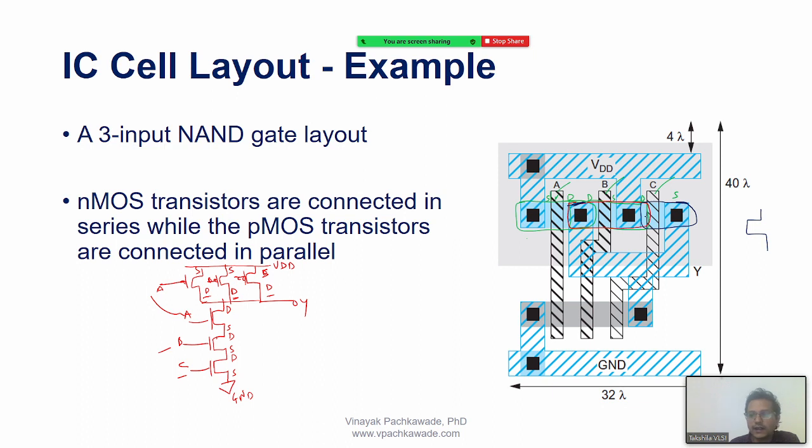Over here. Yes. So now one end of this transistor is connected to the source, to the VDD. Where is the connection to the VDD? Look, here is the connection to the VDD, and here is the connection to the VDD. So can I see that all my three transistors in the pull-up network, which is nothing but the PMOS, have their sources connected to the VDD? Yes, sir. Yeah, this could be source and this could be drain, right? Yeah, so now that is done.